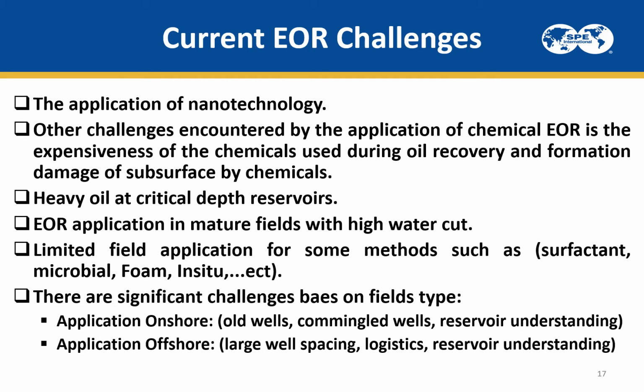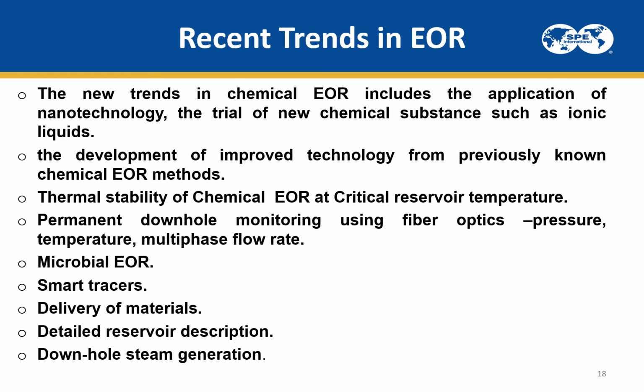For offshore it is also the same, the reservoir description. Besides, the logistics of mobilizing the equipment or EOR material offshore is very challenging. Besides, most offshore fields have a large unit spacing. This is very challenging for the spacing between injector and producer. In this case, the response will take a lot of time.